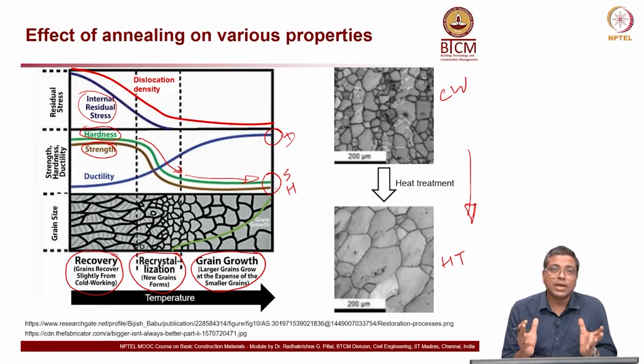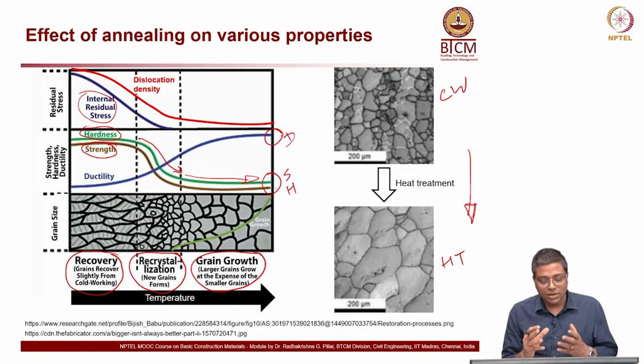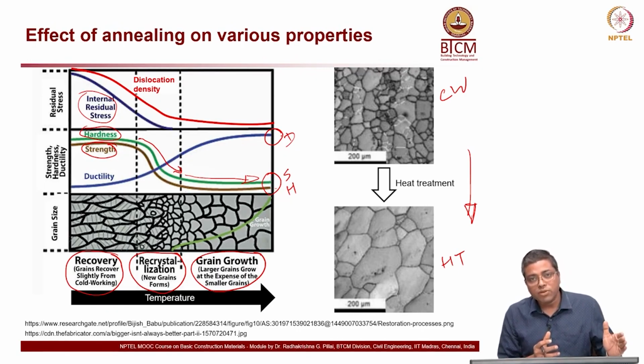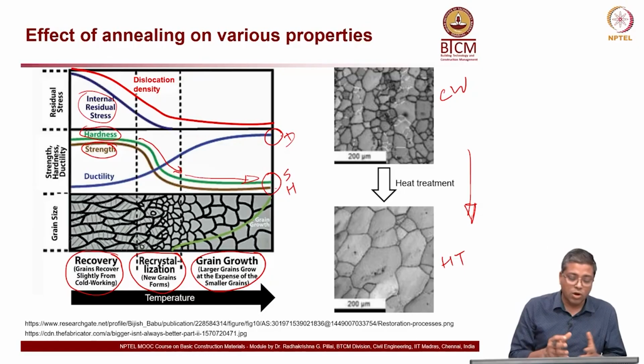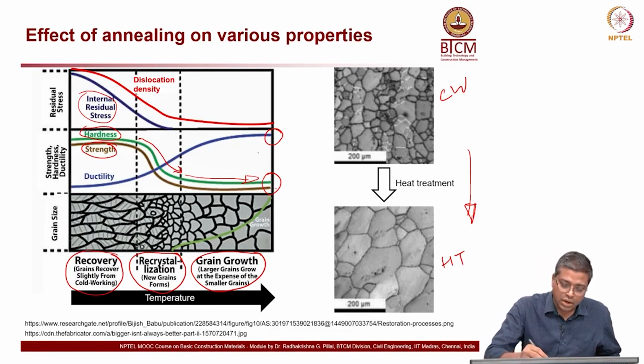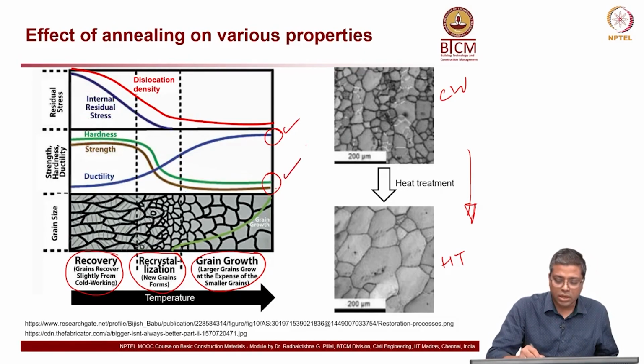All those target values for these properties will be given at the time of design, and then the steel manufacturer has to adjust the composition of the material, I mean the raw materials which are put in the molten material, and then the manufacturing process, the cooling rate, or how many times you do these heating and cooling treatments, etc. All that has to be fine tuned so that you get these target properties, okay, this and this.